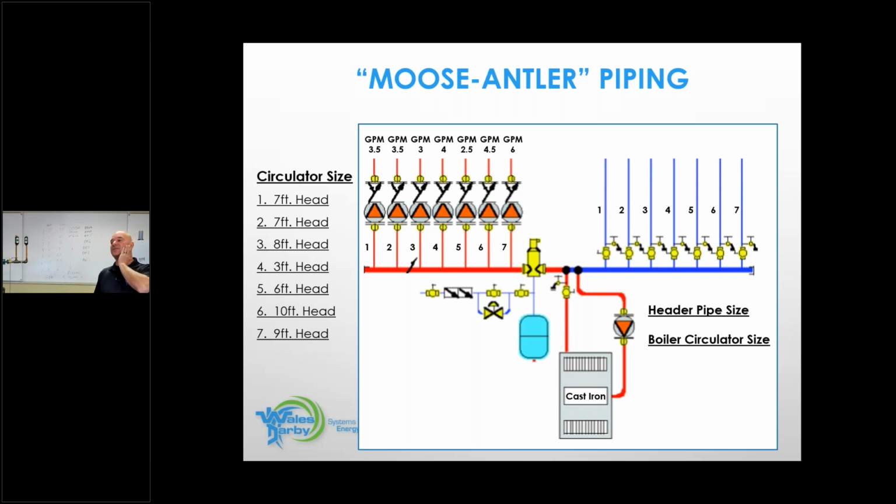If you did this with AC circulators and sized it correctly, these are typical heating zones. This is not like we've made a stretch here. These are typical head drops, typical flow rates. They're 25,000 BTU circuits, 45,000 BTU circuits, 30,000 BTU circuits. So they're all legitimate sized circuits. This one down here with 6 GPM, that would be a 1-inch circuit, right? This is what you would need on the AC side of the circulator world in order to achieve the same job. So these ECM circulators give you a wider window of operation.